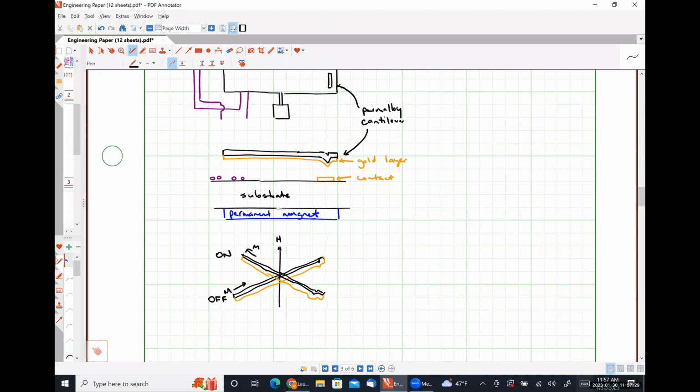Whereas when we talk about electrostatic switching, we'll find that it requires a particular voltage to cause actuation and then a smaller voltage to maintain the state, but it's always consuming DC power. The issue with this is that it's not CMOS compatible by any stretch of the imagination, because it requires electroplating and the application of permanent magnets and all that kind of good stuff as well. So, all right, that is enough out of me for today.